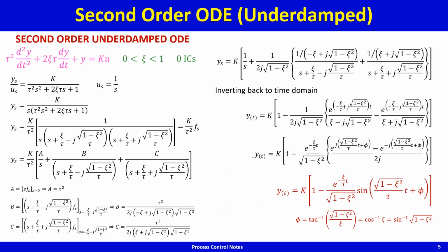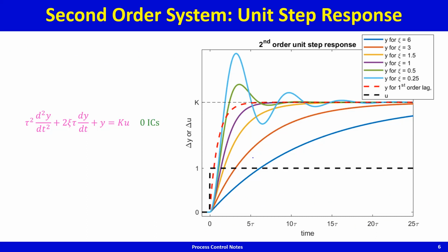And what I did was, so we've looked at overdamped, critically damped and underdamped. So I just took a system and got its response as chi was varied from a large value, that means highly overdamped, and I kept reducing chi from 6 to 3 to 1.5 to 1. This is critically damped. Underdamped 0.25, and you can see this is what you got when you have chi equal to 6. This is what you get when you have chi equal to 3.